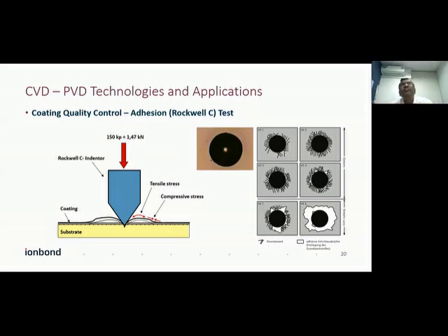See, basically, these coatings are done in high vacuum. So casting is having the high porosity. So there is one or two additional processes we need to carry out to overcome the degassing from those porosity of the casting. But certain coatings are possible on the casting.